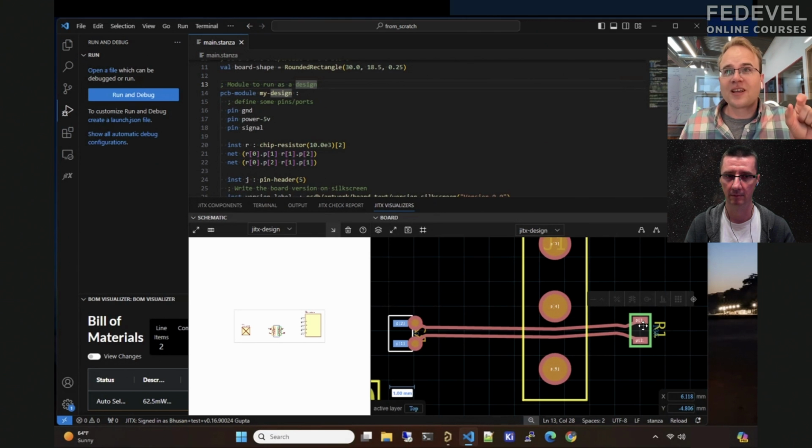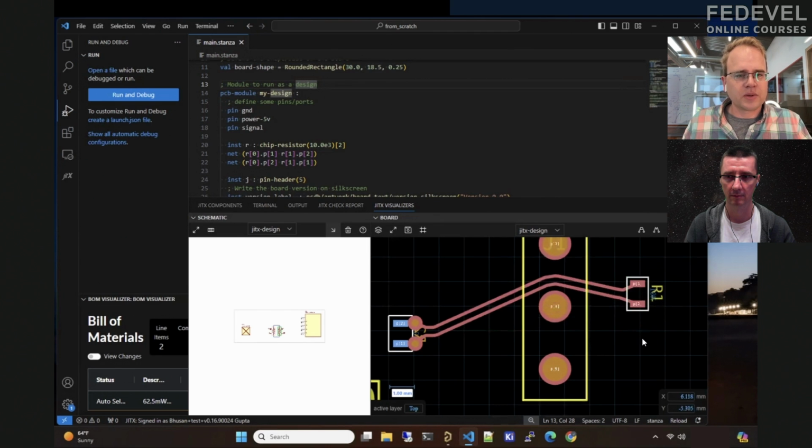You have to make sure that, I think over the span of 20 millimeters per route, you can't build up more than 1 picosecond of skew in your differential pair. So you have to do this instantaneous deskewing, which we can do automatically because we know what it's for, and you've given up the control so that it will be able to do that. But that kind of thing is really hard to do in existing tools. Even just any angle differential pair routing is kind of tough.